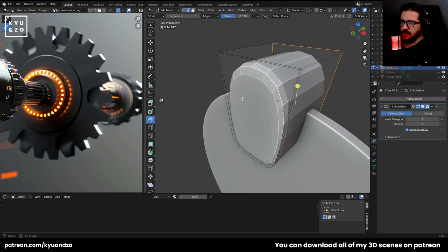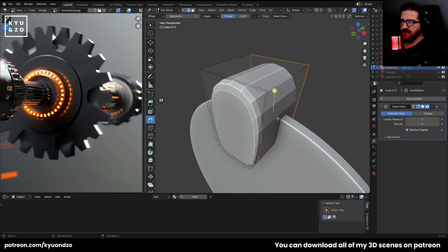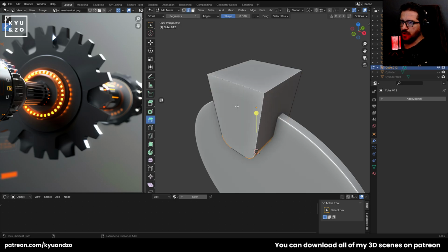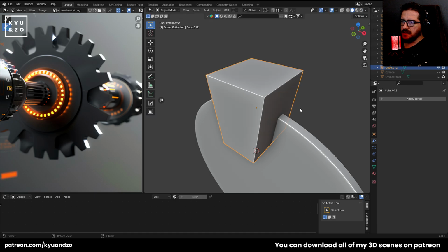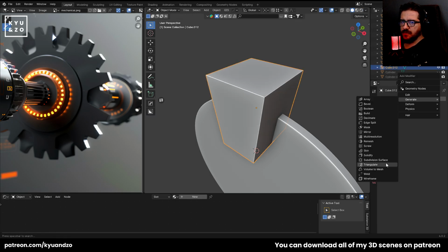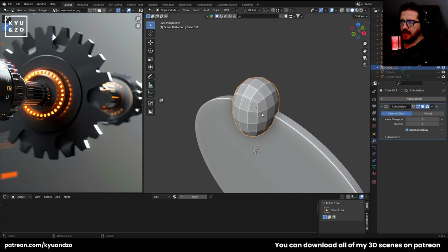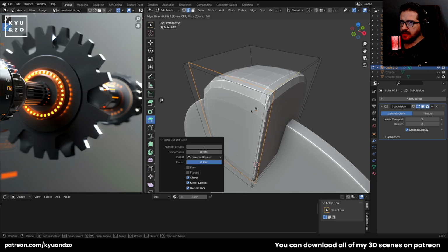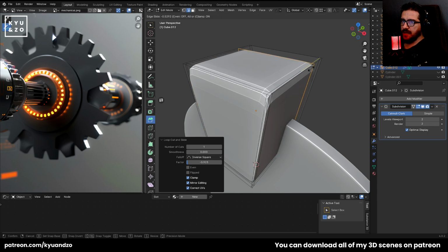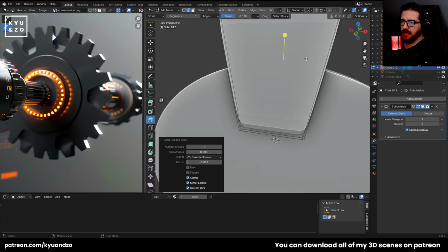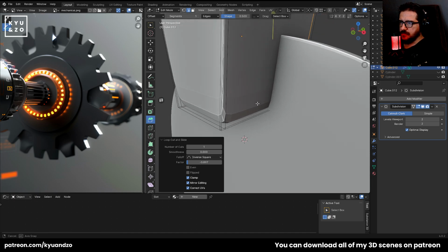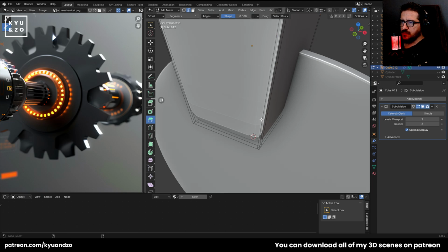Look at this, we already have problem because we added bevel and go back. No, no way. I just need to play with the subdivision surface. Because if you add edge loops early, or I mean bevel, you can make it just like this, okay? That's the problem. So you need to make a plan and stick with it.